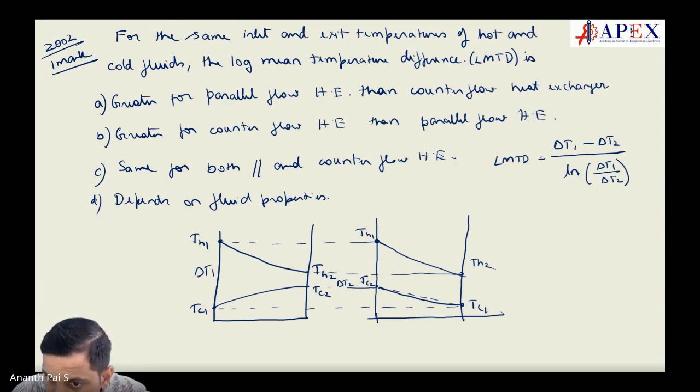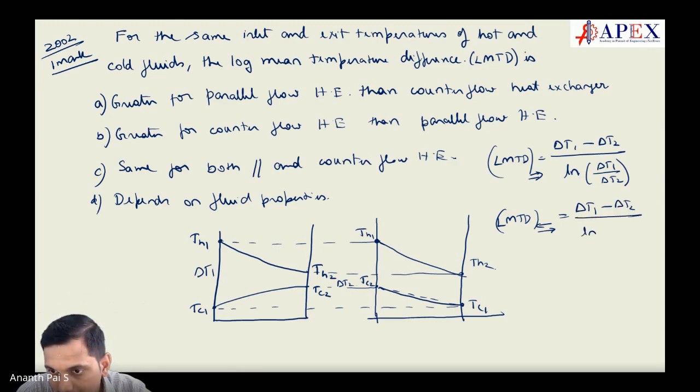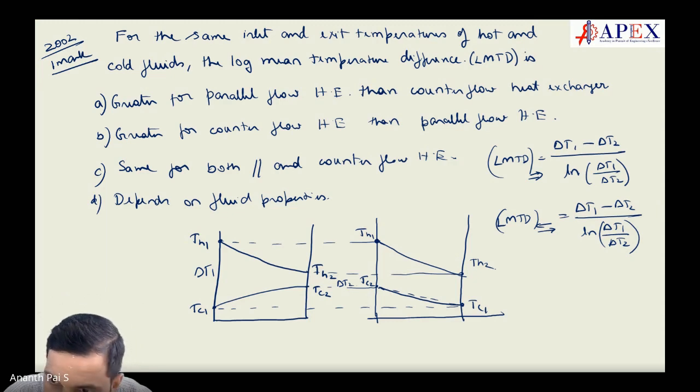Here the difference is between the big and the small number. Now this is parallel flow. I'll write it like this, parallel. And then the LMTD for counter flow, I'll say delta T1 minus delta T2 divided by log of delta T1 by delta T2 for the same one. Now, delta T1 will be delta T1 for counter flow, TH1 and TH2, right?